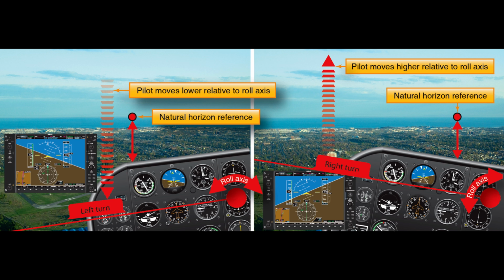For example, diving when turning right and climbing when turning left in airplanes is common with stick controls, because the arm tends to rotate from the elbow joint, which induces a secondary arc control motion if the pilot is not extremely careful. Likewise, lowering the nose is likely to induce a right turn, and raising the nose to climb tends to induce a left turn. These actions would apply for a pilot using the right hand to move the stick. Airplanes with a control wheel may be less prone to these inadvertent actions, depending on control positions and pilot seating.